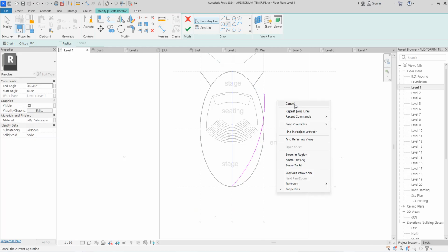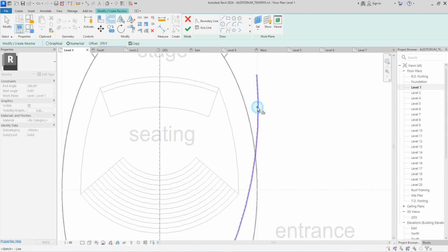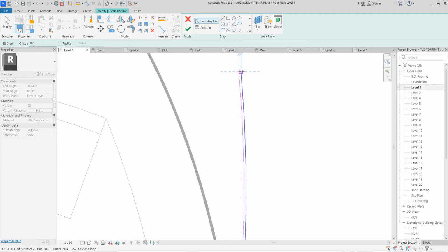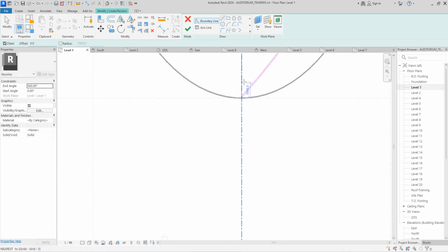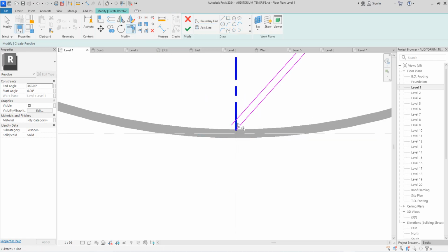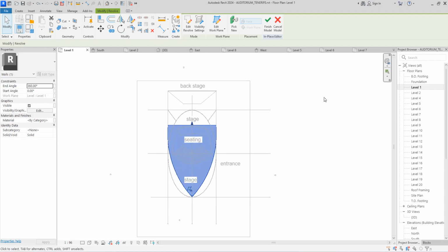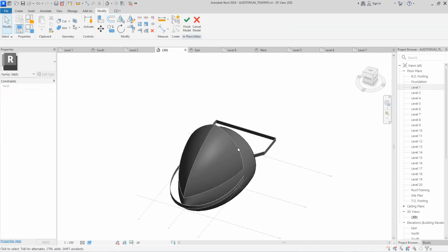So when we have it like that, click finish. No, sorry. Before finishing, you offset it the same way we did before, in 200 mm. So you close this gap up and you close this gap up. So you click by developing it straight up, then you click finish. After you do the finishing work, you go back to the 3D and flip it to see it being done. So let's say 3D here. So this is what you have created.